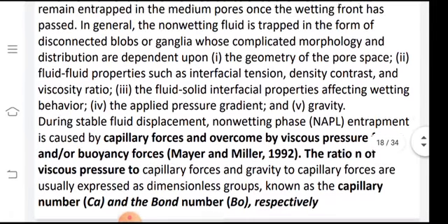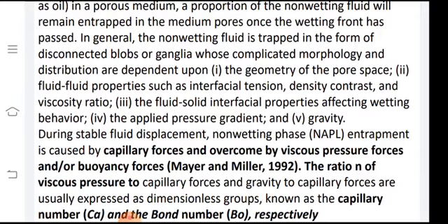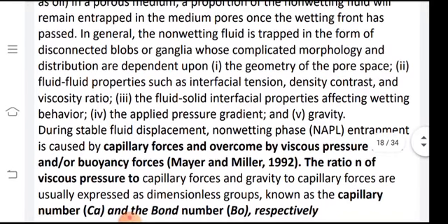So it is something about the aqueous phase, where we have two fluids. One is wetting fluid, that is water. The other one is non-wetting fluid, which is oil. So both of them will have separate behavior. Once the wetting fluid, water, moves forward, then the NAPL in most of the cases will not mix with that water.